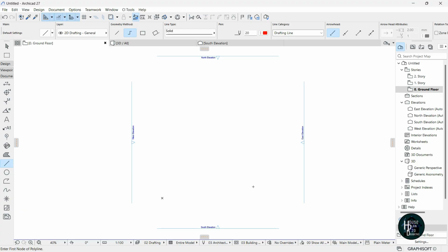Now I want you to give a distance from the bottom surface here. Just click here, drag it like this, and let's give a distance of 7244. Click enter on your keyboard.